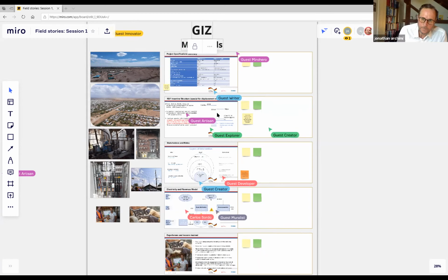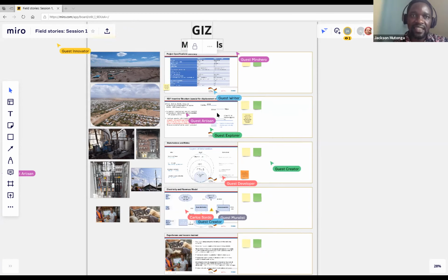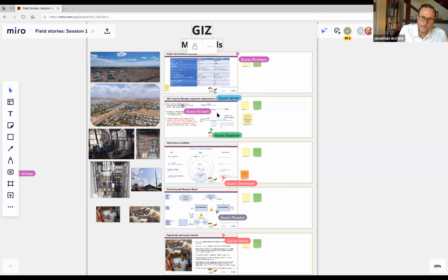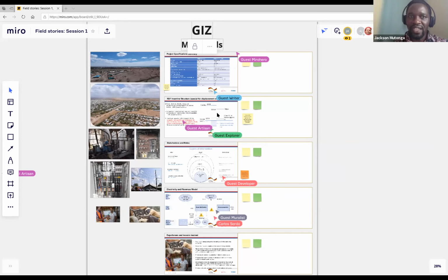So what the regulator does, he gives the private company a 20-year license to operate this mini grid in this space with exclusivity. And within those 20 years it is mandated to provide reliable electricity, where the regulator monitors the service, the quality of service, and also financials.